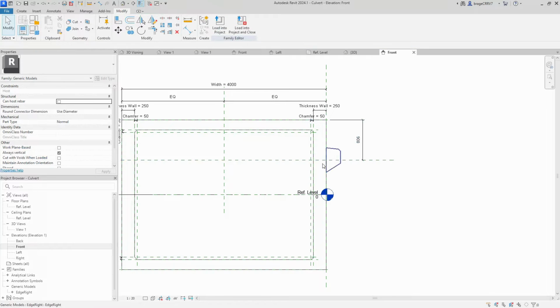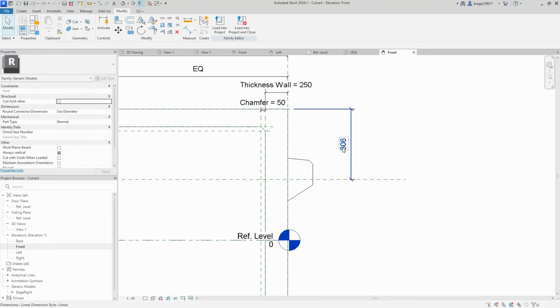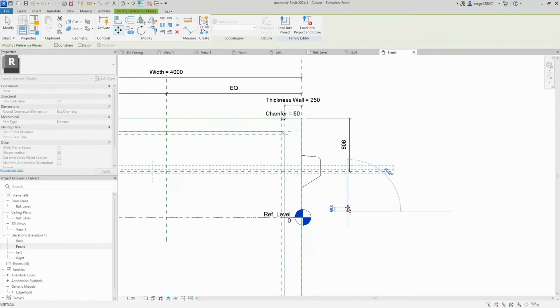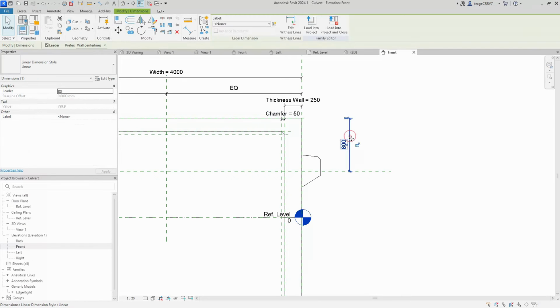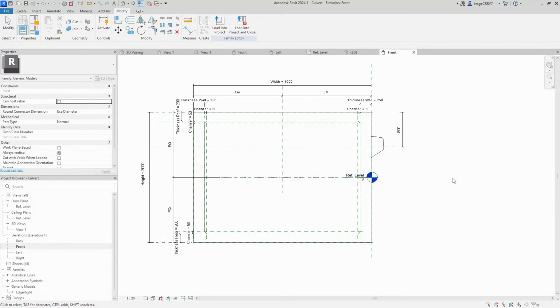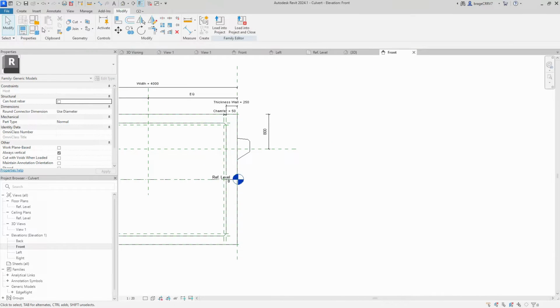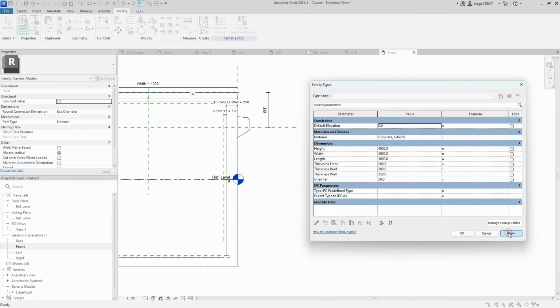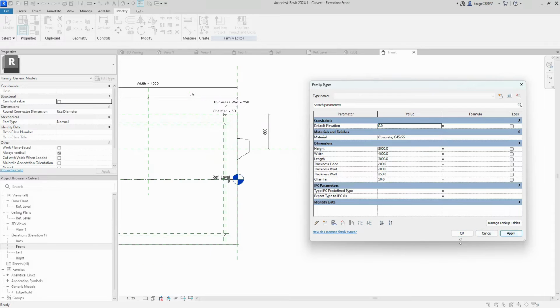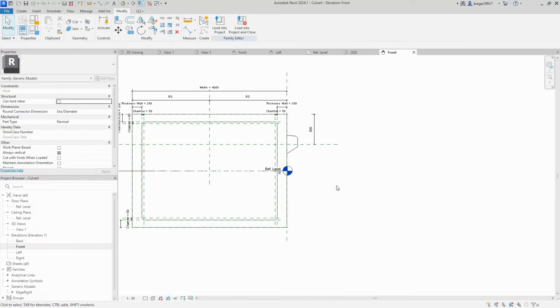We generate an annotation ensuring the number is aesthetically pleasing and lock the annotation, fixing the distance from the top reference planes. This ensures that the edge geometry distance remains constant when altering the height. We perform a quick flexibility test on the height to confirm the distance remains consistent. We proceed by connecting our parameters in the host family with the parameters in the nested family.